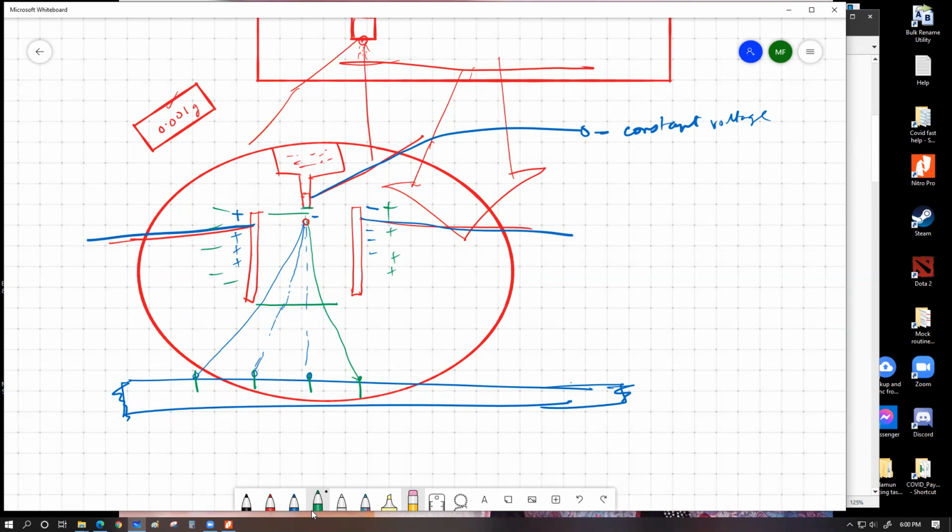So you have to pretty much precisely control the charge amount on this droplet and also the mass of the droplet, so that you can actually control how much it is going to bend, because a heavier mass would have less acceleration, a smaller mass would have a higher acceleration. So if you produce different size or different mass droplets, you're going to have a mess over here. I mean, you cannot place all the points in a specific location. So we're keeping these two constant.